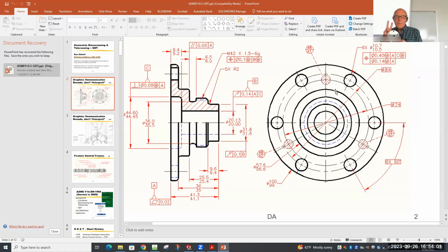You can't have two separate tolerances controlling the same thing. The composite frame controls not the same thing. One controls the pattern, the other controls the holes inside the pattern. But you cannot also have a tolerance on the dimension that locates the starting point for those holes. So that's a positional tolerance. If you take a look, what controls where those holes are?